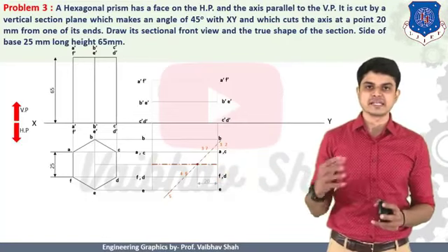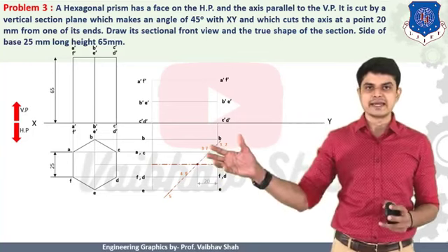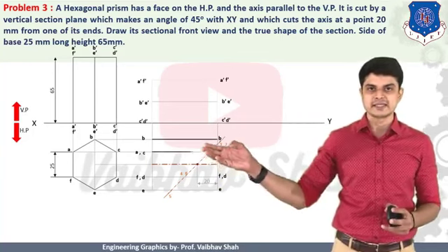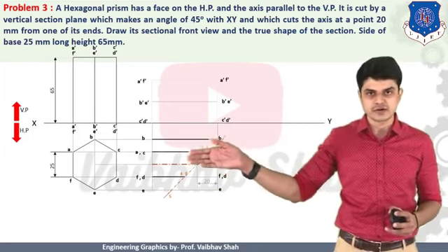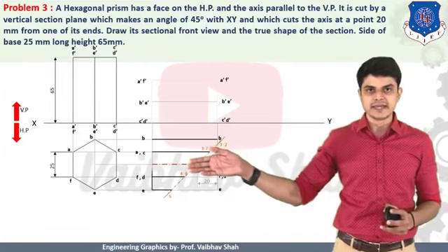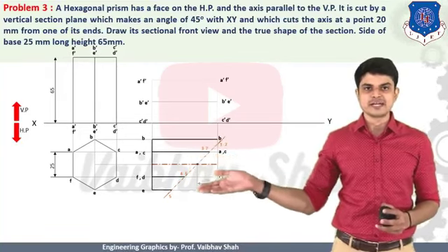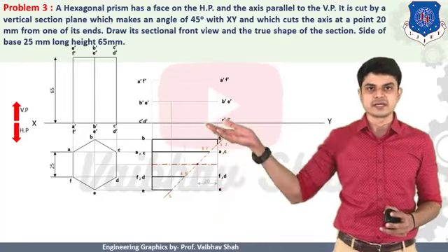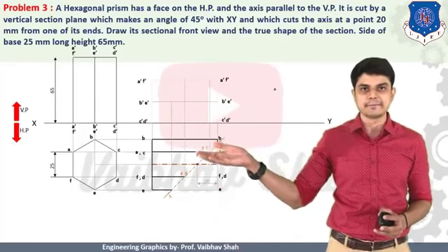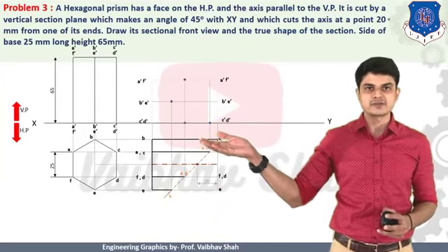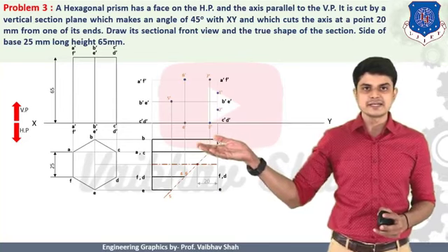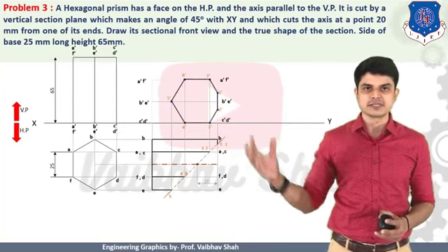So let us make the left hand side portion on the cutting plane line a diagram like this. We will be making this portion on the left hand side of your cutting plane dark. Therefore, we should transfer each and every point onto these vertical lines. We should identify and mark the corresponding points on this line like this. So these are nothing but our required points, and you should connect these points.